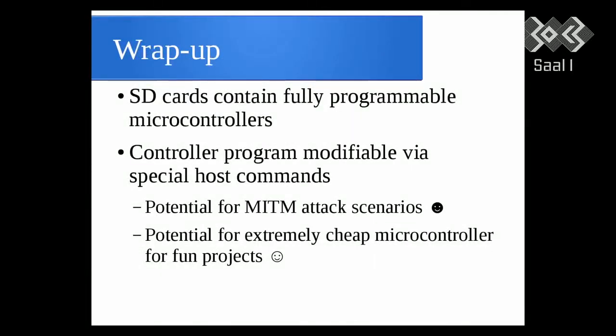So, to wrap up, SD cards and any sort of flash type memory will contain a fully programmable microcontroller, perhaps a very powerful microcontroller. This applies to SD cards, microSD cards, eMMC, SSD, USB controllers. The controller program we have demonstrated is modifiable via special host commands, and these are typically not locked out because of the complexity of the flash memory space.